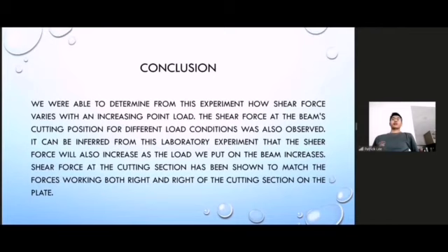Conclusion: we are able to determine from this experiment how shear force varies with an increasing point load. The shear force at the beam cutting position from different load conditions was also observed. It can be inferred from this laboratory experiment that the shear force will also increase as the load we put on the beam increases. Shear force at the cutting section has been shown to match the force acting on both the left and right of the cutting section on the plate.